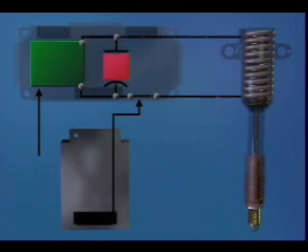300 volts from the ICM coil driver flows through the primary windings of the coil-on-plug resistive coil. As the magnetic field is created by current flow in the primary windings, it induces a voltage in the secondary windings of the coil. Voltage rises in the secondary windings till it overcomes the resistance caused by the gap between the spark plug center electrode and the spark plug ground strap.